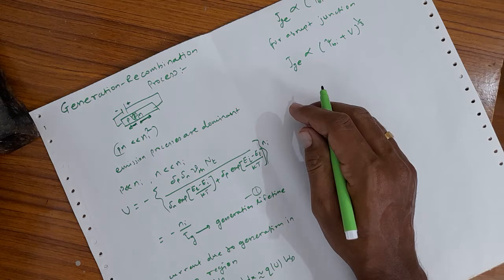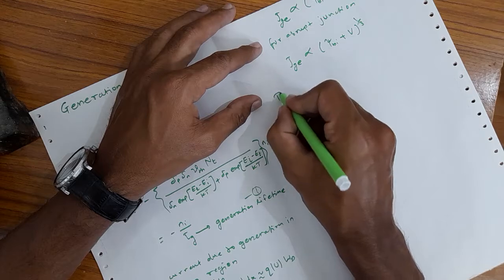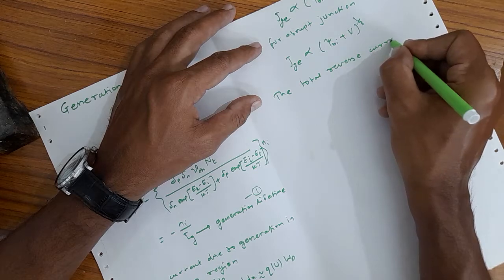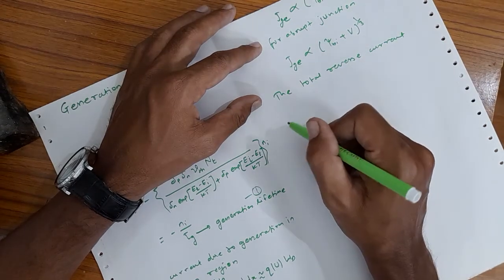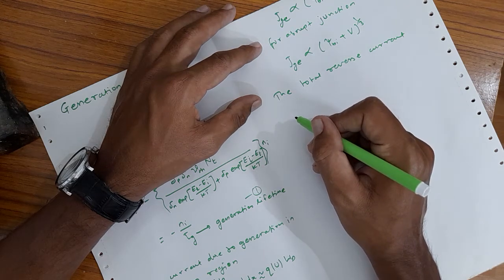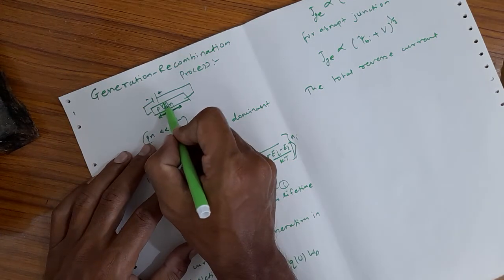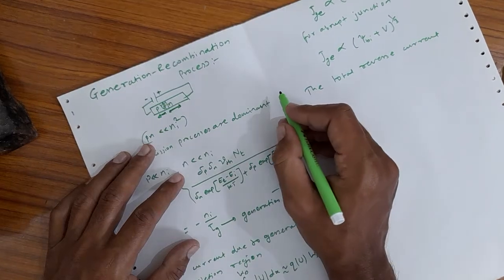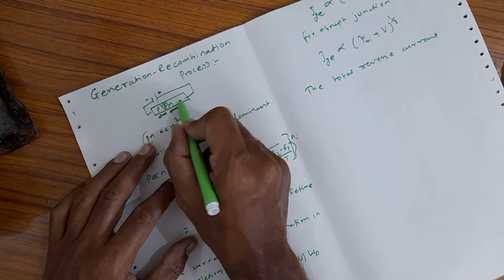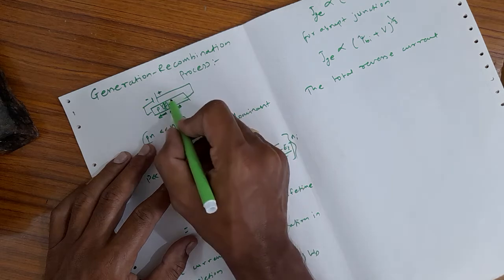Now let us talk about the total reverse current. For the given condition, it can be approximated by the sum of the diffusion component in the neutral region and the generation current in the depletion region. Other than the depletion width, the remaining part is the neutral region.